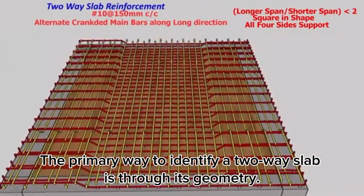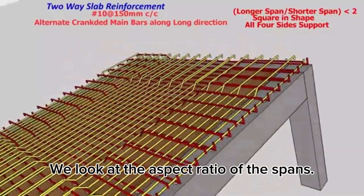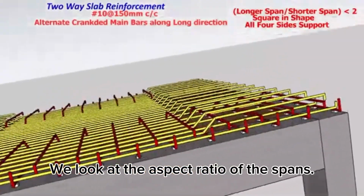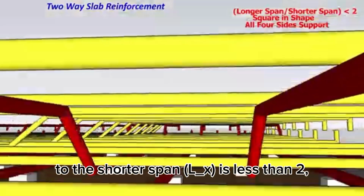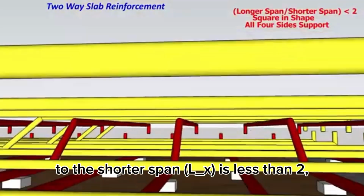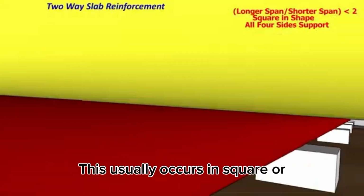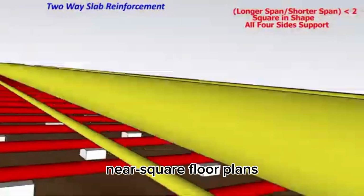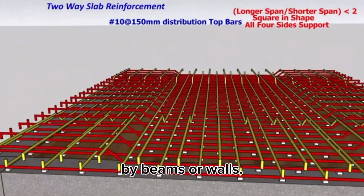The primary way to identify a two-way slab is through its geometry. We look at the aspect ratio of the spans. If the ratio of the longer span Ly to the shorter span Lx is less than 2, the slab is classified as a two-way system. This usually occurs in square or near square floor plans, where all 4 edges are supported by beams or walls.